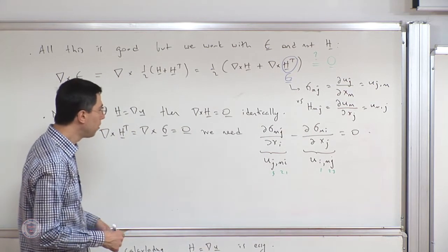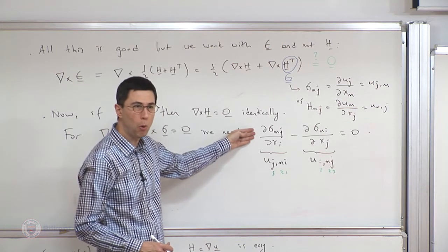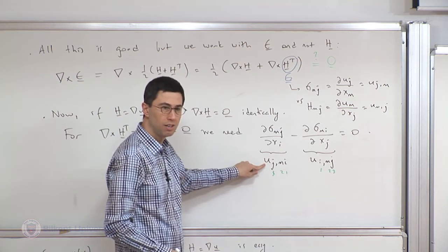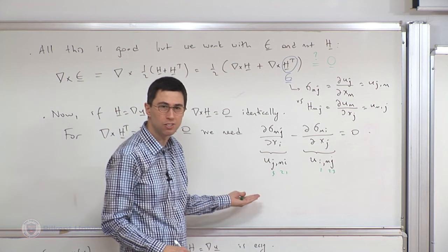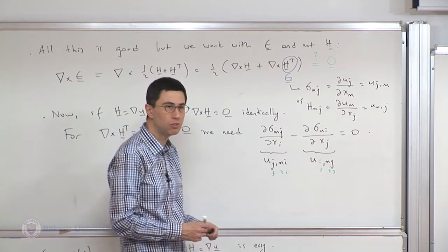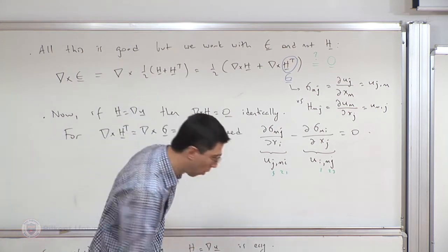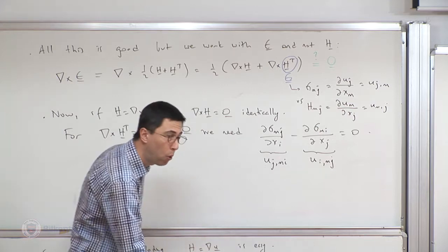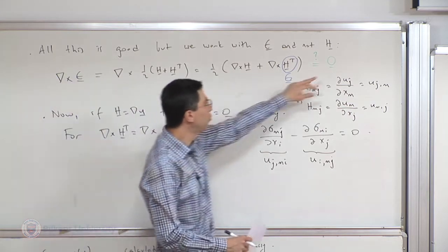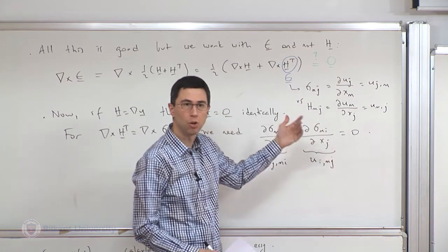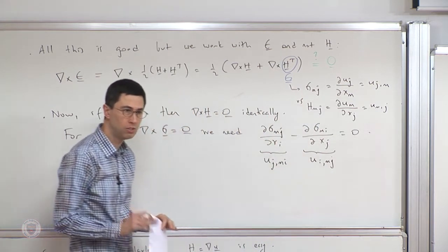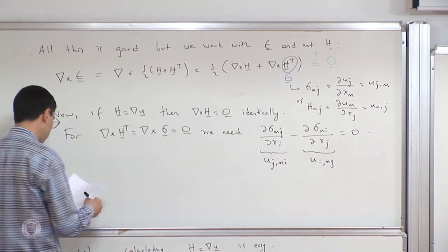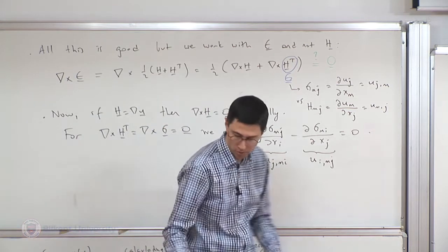In other words, now this has become not only a requirement, it's an impossibility, because even when I put in the actual displacement field, it's not satisfied. So it should have been satisfied if this was a meaningful condition. So the conclusion is that I cannot require the curl of epsilon to vanish to ensure that epsilon is compatible with the existence of a displacement field. That's the message here. It's not good enough. I need to do something else. So that's the conclusion, and let's write that over there.